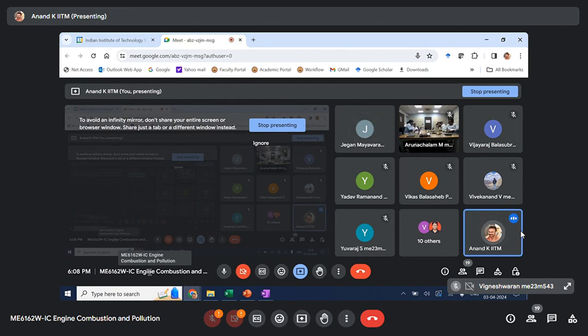After TDC is written with a positive sign, and B TDC is written with a negative sign, because the nomenclature generally followed is, if you use A TDC everywhere, then positive sign means it is after TDC. Negative sign means it's before TDC. This is just a standard nomenclature, but nevertheless, you can consider piston TDC as a 0 angle. Understood, sir. It's clear, sir. Thank you, sir.